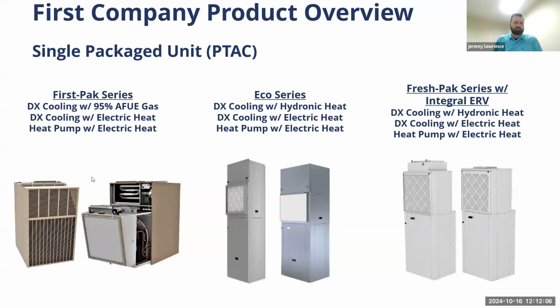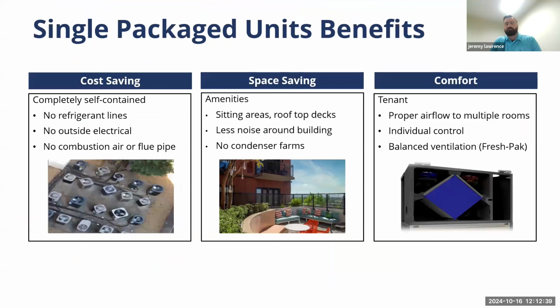The FirstPack series, which we'll talk about a little bit at the end, is a competitor to that Magic Pack, Napoleon Condo Pack sized unit and sleeve, modular, high efficiency gas heat, electric heat, and electric heat with heat pump backup. And the real star of the show today is this Fresh Pack with integral ERV. So heating, cooling, and fresh air all built into one unit. And that is really the big game changer that FirstCo brought out a few years ago.